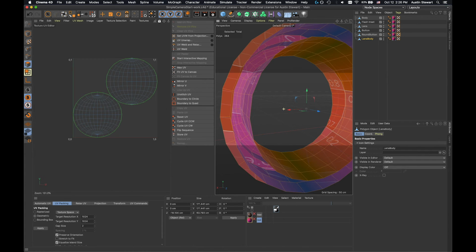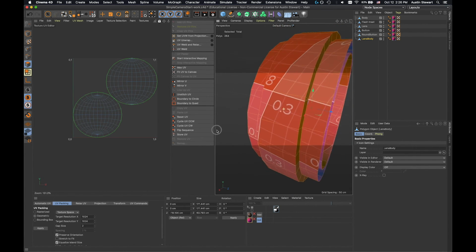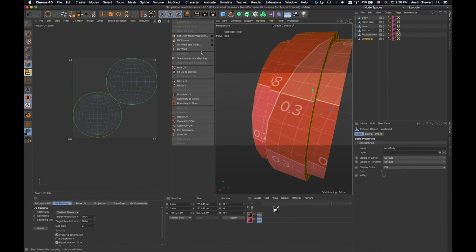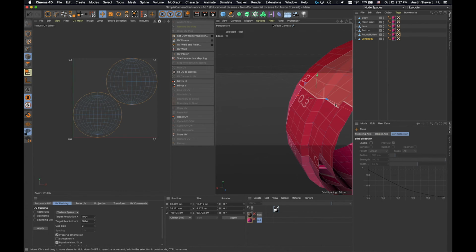It's cylindrical, and it's got an opening on one side. And because of the way it's shaped, this should allow us to use this thing called a UV peeler to peel this thing apart. And so I'm going to go ahead and try that. So the first thing we need to do is go to Edges Mode. And we need to rotate around here. I'm going to double click, I'm going to use the Move tool or something.